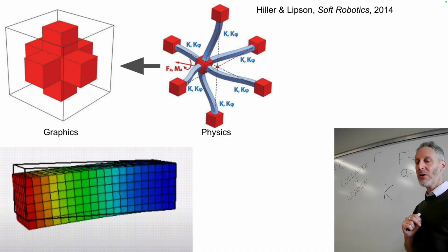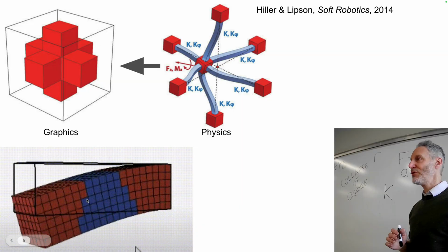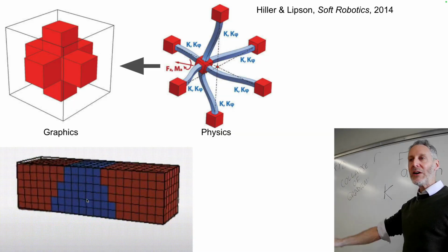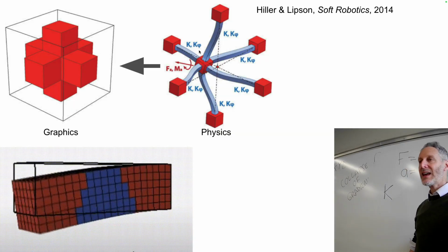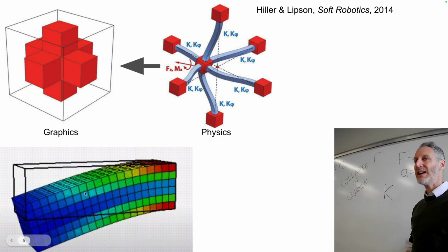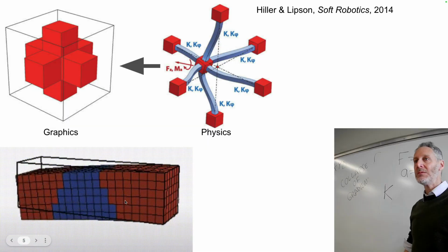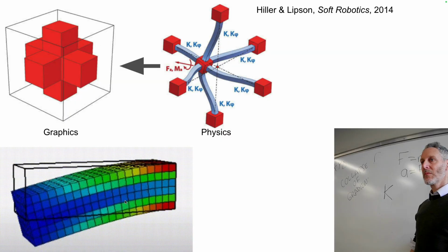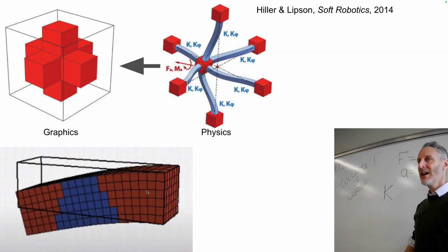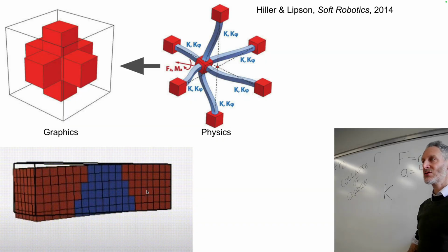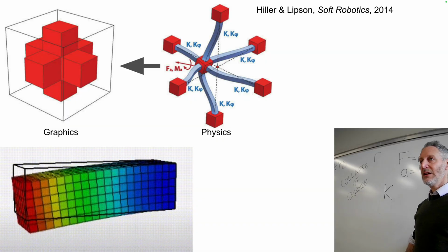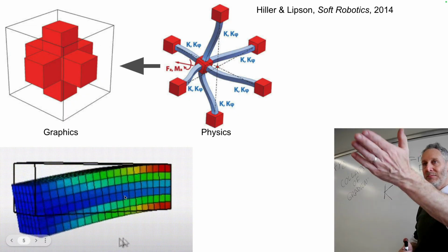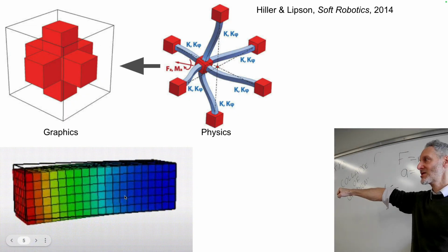So far, so good? Okay, if we were to take this particular collection of voxels, and you got to imagine pairwise connections between neighboring voxels now, and we were to paint very high numbers across all the k and the k phi's for every beam inside here, and then we simulated this one big beam, how would it behave? Each of these little beams inside has 6 very high magnitude numbers associated with them. Each pair of neighboring voxels is attached with very stiff connecting beams. How would this overall construction behave? It would just kind of sit still, right? Just stay still, right? It's a steel beam.